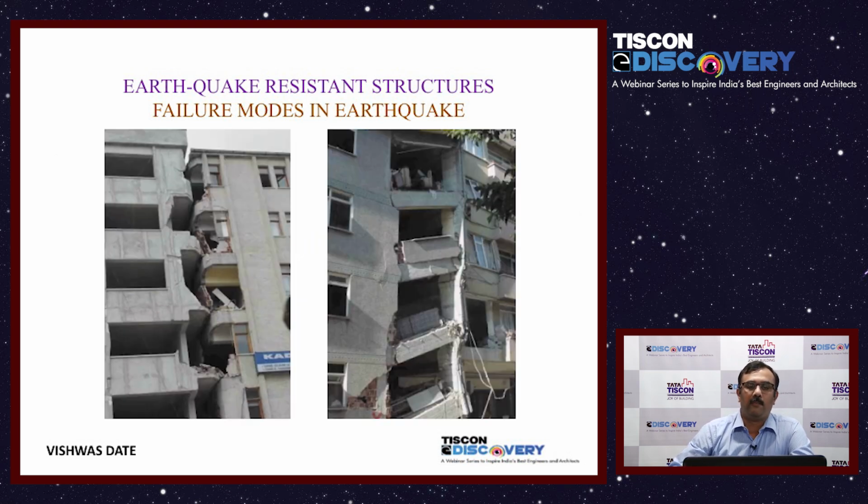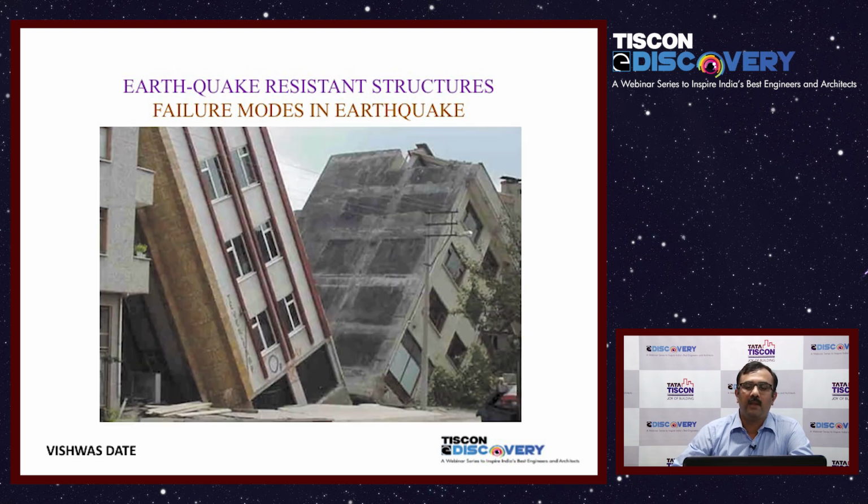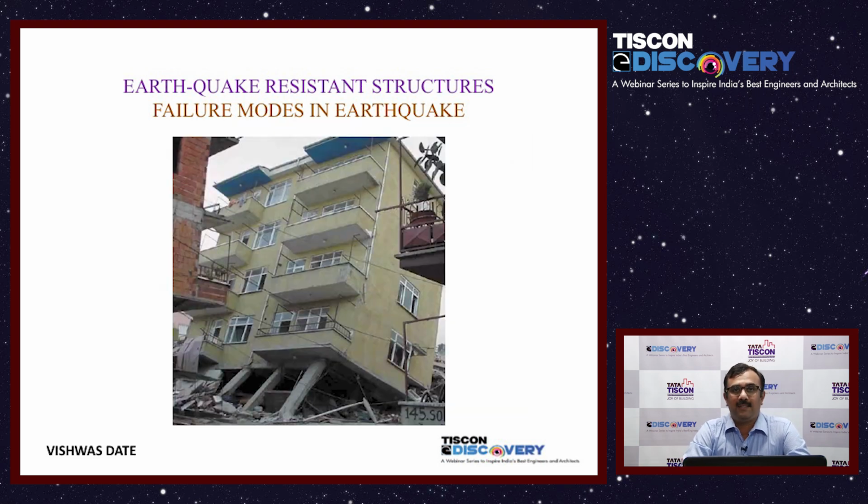What we talked about, compounding of buildings, very classic photo. You can see the buildings on both sides have different story heights. Probably the buildings have performed individually good in earthquake, but because they were too close, they have actually hit against each other. Similarly here, you can see this building and this building. This part of the building is not absolutely affected. Also, perhaps here the damages are more local, but because they were too close, they hit each other and these junctions have given away. Now, do we want these? This is one of the classic failures of earthquake.